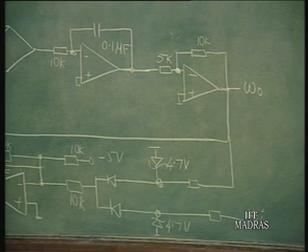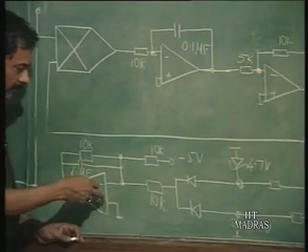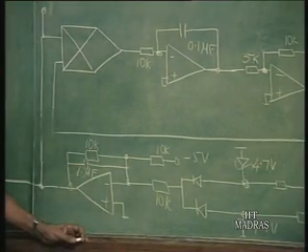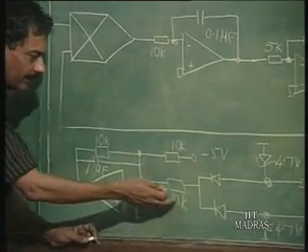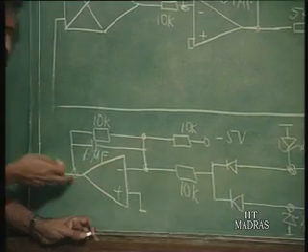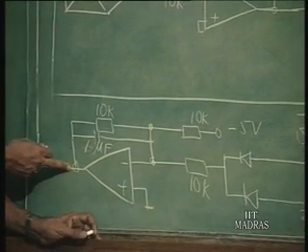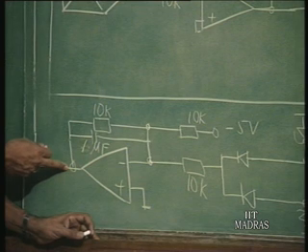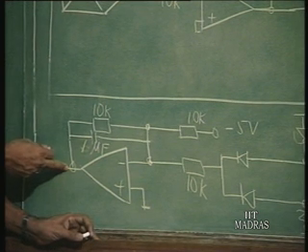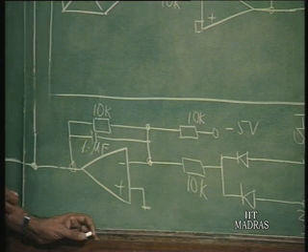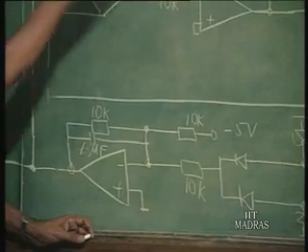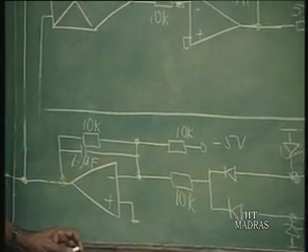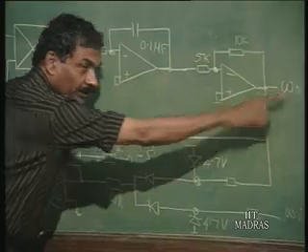And obviously, the low pass filtering is going to be done by this op amp here, and the gain has been fixed at 1, so that the sensitivity is slightly reduced. Earlier the gain was pretty high, and when the gain was high, this DC voltage was also high, the op amp was going to saturation, and we could not very clearly see the actual theoretical limitation of the lock range. Here now you can clearly see the lock range and how this phase lock loop will get locked to the incoming frequency, which is here, and this is the output frequency.